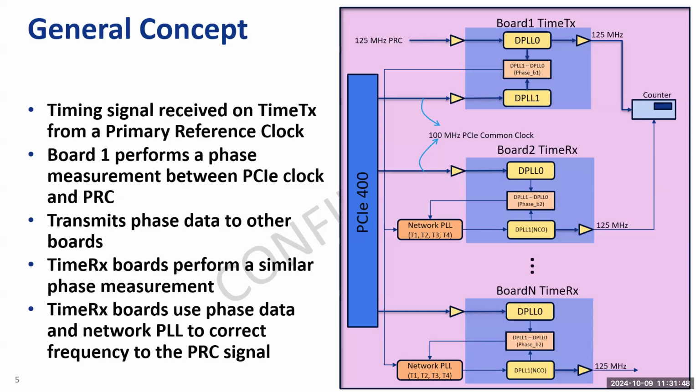It's an approach that we want to look at because, as you highlighted, one of the difficulties with data centers is there's no way of nicely getting clock information from one board to another, one peripheral board to another, or NIC board. So that's the challenge. We're trying to find ways to do it. This presentation is highlighting a method that is very useful and can be used, but it does have some challenges that were not seen in traditional ways it was used in the past in telecom. We didn't have concepts of spread in telecom, right? So you didn't have to worry about it.